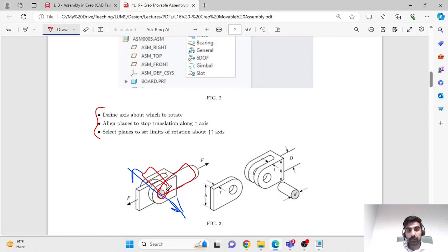You need to manually prescribe that this pin motion is permitted between these angles. So that's an optional additional constraint in a pin connection that you can add, which is this third bullet point over here.